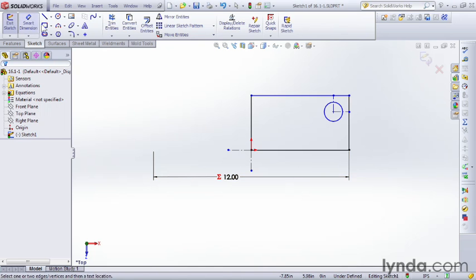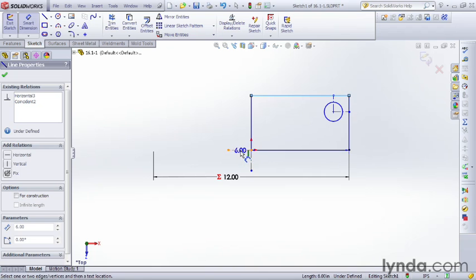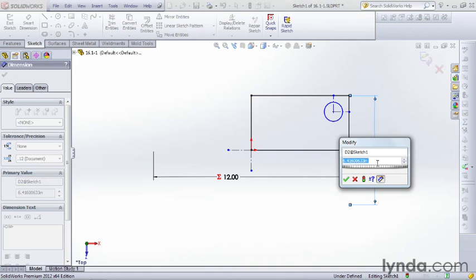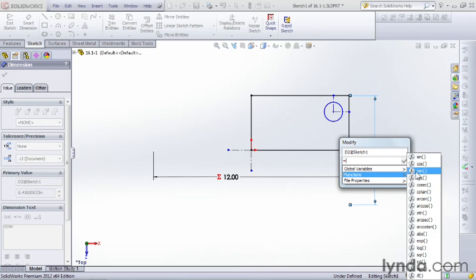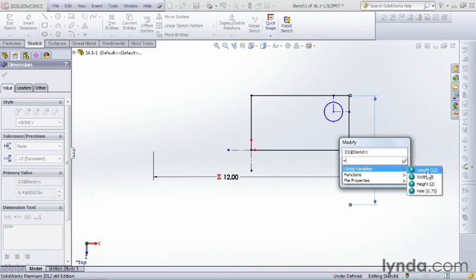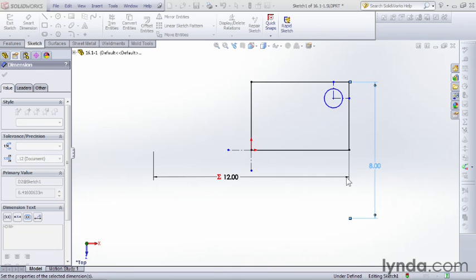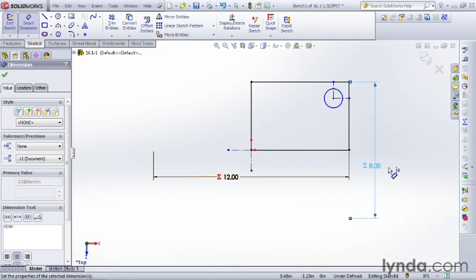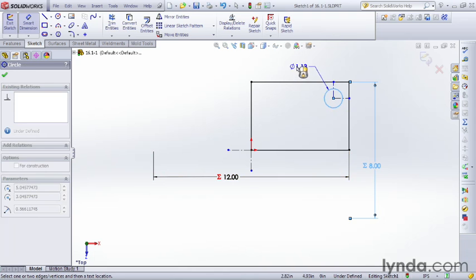So click on the sketch dimension. I'm going to click here across that center line value. And this time, if I want to link that to something, hit the equals again. And now I've got these global variables. They're already assigned. I can just go grab one of those, right? So I want the width this time. I say width and click OK and it just inputs that value. Okay, I've got a few more that I can input here. I can say this value here, we want a dimension on that.